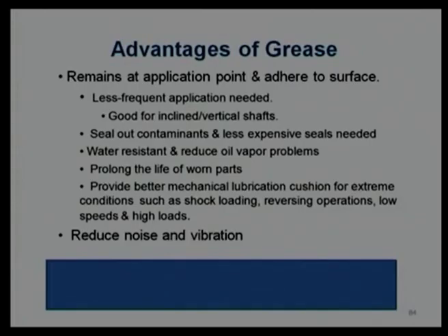It reduces the vibration, it reduces the impact loading, it can sustain shock loading. So, we say that it gives maximum comfort. That is why with most rolling element bearings, even if they develop small pits on the surface initially, they can be used effectively with greases, and that will give good results.